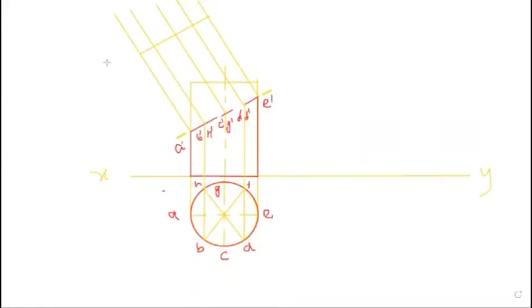So first we choose this axis. This is parallel to A dash E dash, and we give it the name AE. So here we give the name: this will be A1 and this will be E1. Means you just project this top view here on this line.